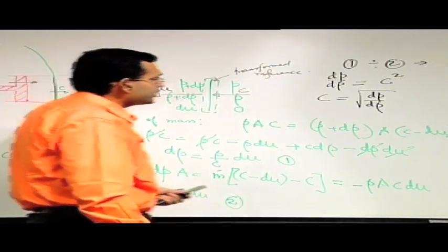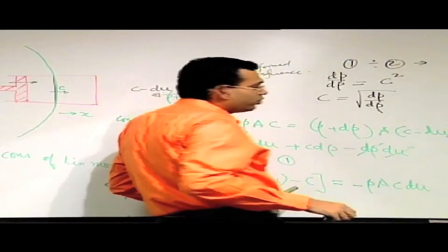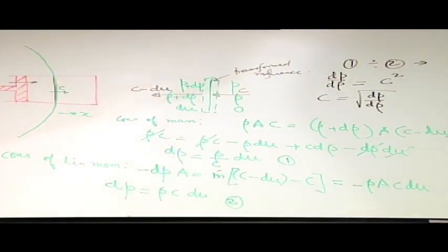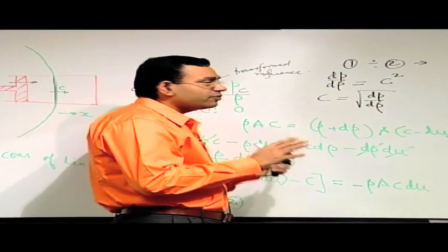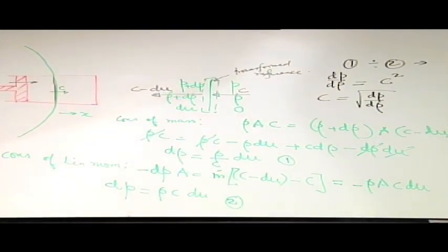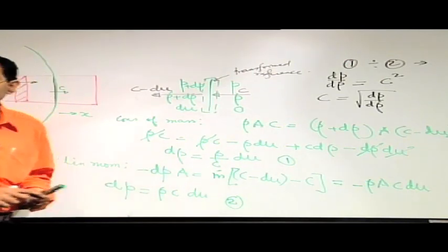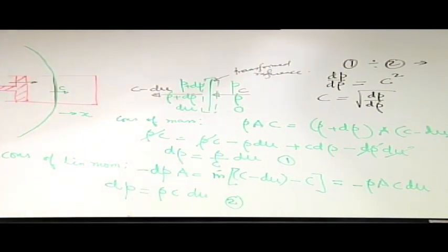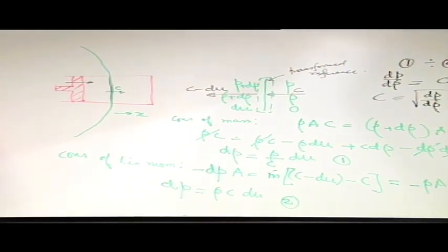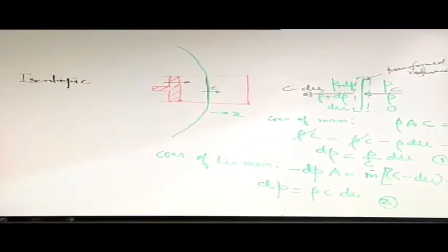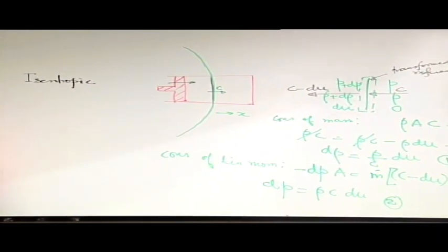The next important question is that when you write dP d rho, it depends on the thermodynamic process by which it is occurring. So to have a further simplification of that, we must refer to certain processes. So let us try to have a feel of what kind of thermodynamic process we are talking about. In most of the examples that we will be discussing in this particular chapter, we will be referring to the special type of flow known as isentropic flow, or the process thermodynamically is an isentropic process.